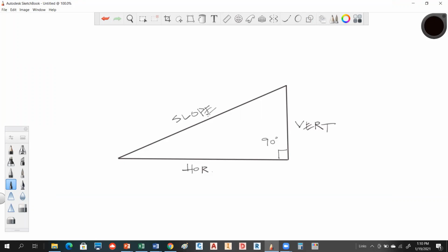It's very important to understand, particularly between these two measurements, because a lot of times people are measuring slope and they think they're doing horizontal. I'm going to show you guys when we get out in the field, a lot of you will do slope distances right away, and we really are referring to horizontal, or we need horizontal. Primarily for layout purposes, these are going to be more important. These are the two that we're really after, but sometimes it's more convenient to do a slope.